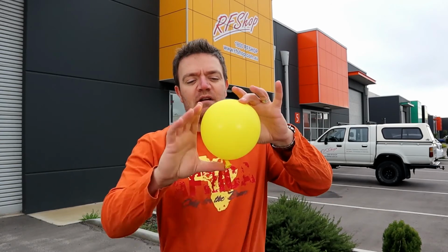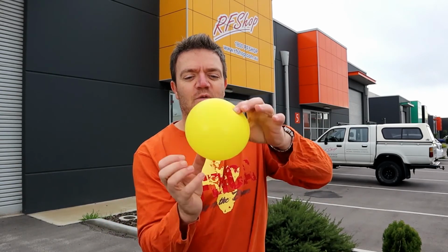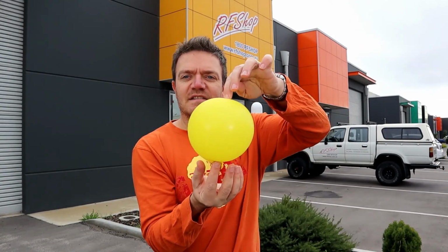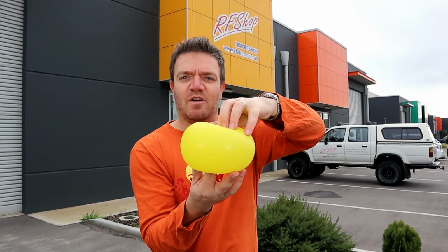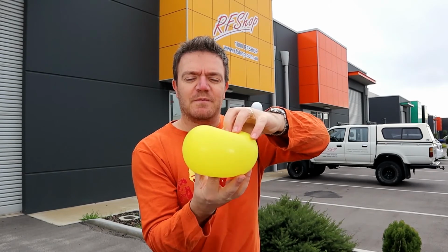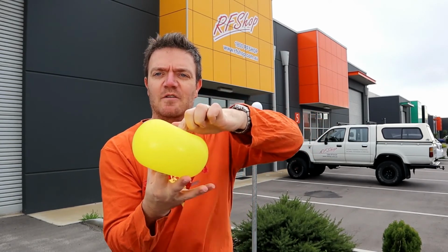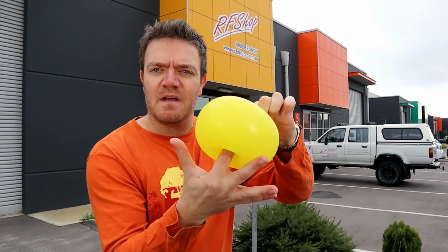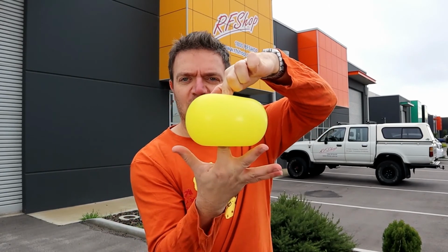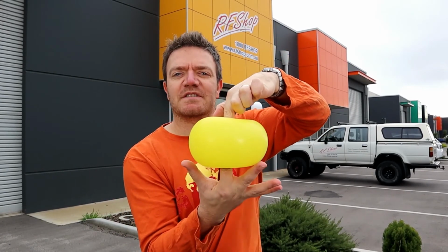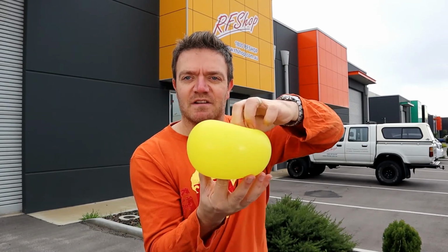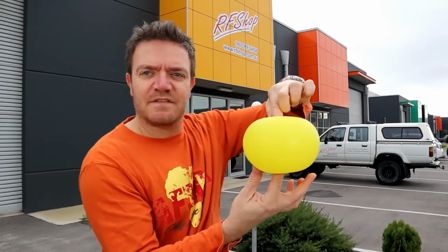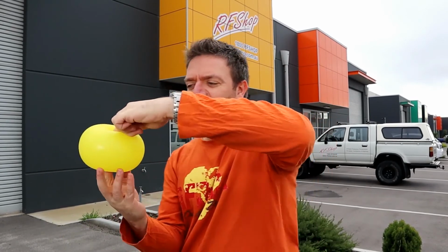What we do with an Omni, you basically, similar to this, you squash the top and bottom and just see how difficult it is with an actual balloon. The thing to watch is, that's nothing. Once you start to squash at the top, the edge just starts to go out. So with a typical dipole, which is just the most basic Omni, you would have a donut shape. So you have nothing at the top, nothing at the bottom. You can see it's a bit flatter at the top and bottom as well, but it has been squashed a little bit to the side, so you have gain on the sides, on the outer sides, and it's an Omni, so no matter how I stand, it always gives you the same performance, no matter what you look at from.